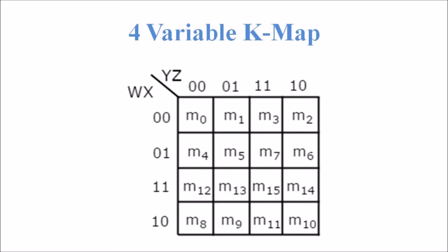And this figure shows how we can represent the 4 variable in a KMap solution. There is only one possibility of grouping 16 adjacent minterms. Let R1, R2, R3 and R4 represent the minterms of the first row, second row, third row and the fourth row respectively. Similarly, C1, C2, C3, C4 represent the minterms of the first column, second, third and fourth column respectively.